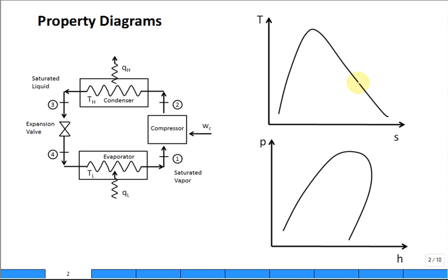So you put at the low pressure at state 1, and this is a line of constant low pressure, and this is a line of constant high pressure on a TS diagram. So if you go from state 1 to 2 and you do it adiabatic and reversibly, you'll get to 2S. It's isentropic. If there are some irreversibilities, you kick it out and there's state 2 actual. And then you cool at constant pressure till it's saturated. So it goes from superheated to saturated vapor.